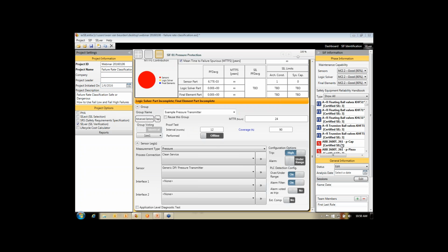So another question here, and that's actually a good question. Just to clarify, that time delay and alarm filter flag only applies if the out of range failures are actually detected. So only if you can detect those out of range signals and flag them as unhealthy can you claim that you have an alarm filter capability.